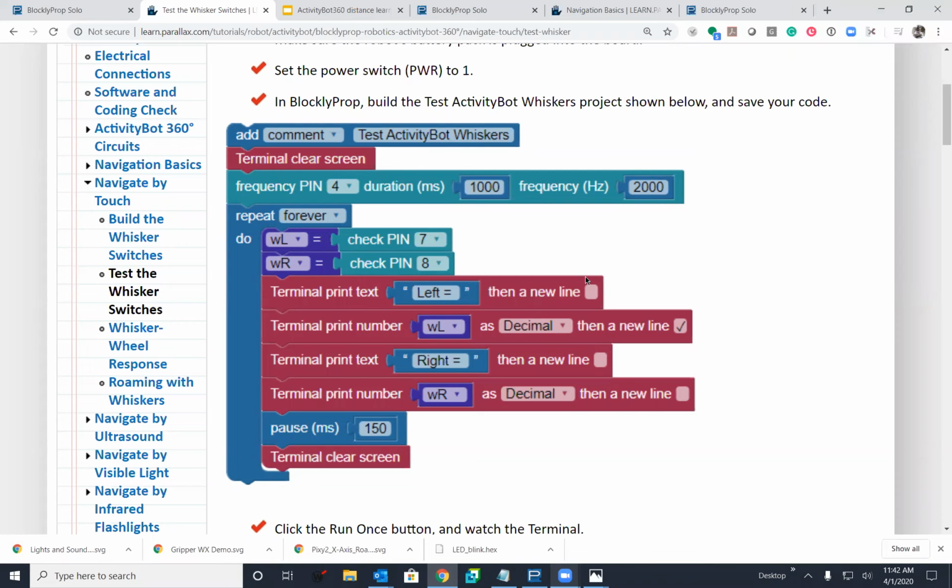In this particular instance, if you just put a robot drive stop block in between a drive speed and a drive distance block, there is no problem then. That's documented in the help. Excellent. So that's in the help. Great. Reference. Oh, thank you, Stephanie. That's also a good hint for me to do the troubleshooting.